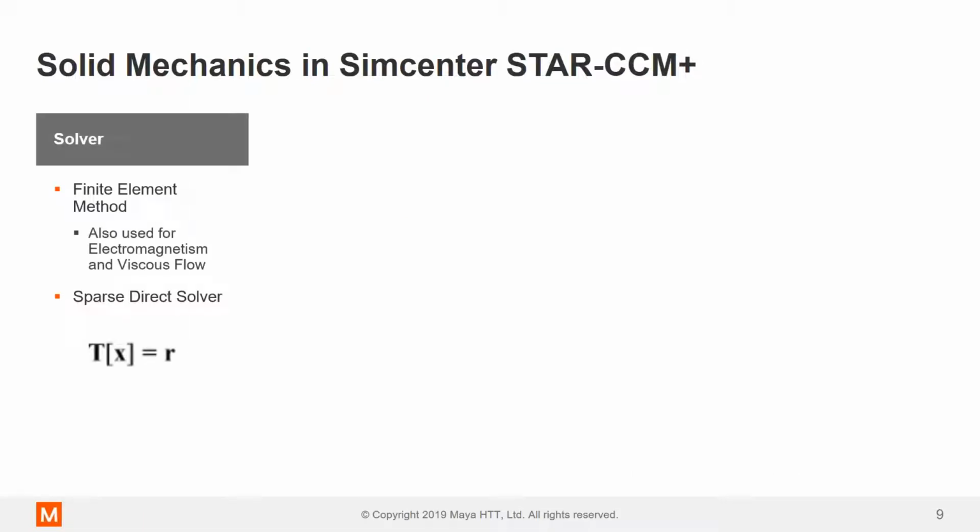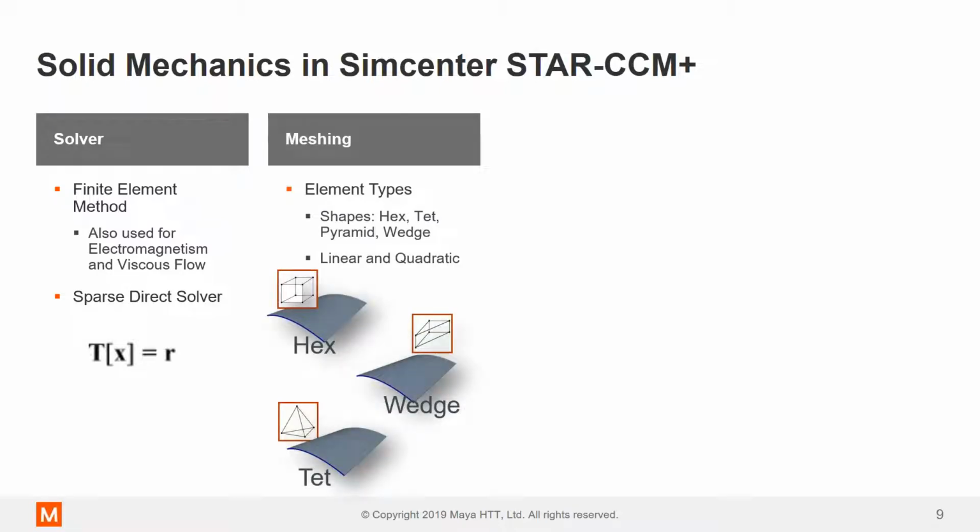Firstly, let's start with the solver. STAR-CCM+ has an inbuilt finite element solver to resolve the solid stresses. This solver is used to resolve electromagnetics and viscous flows. With meshing, we can only resolve 3D solid elements. We cannot resolve 2D, 1D, or 0D elements when running a structural simulation. However, we can connect STAR-CCM+ with Simcenter Nastran to include such elements.